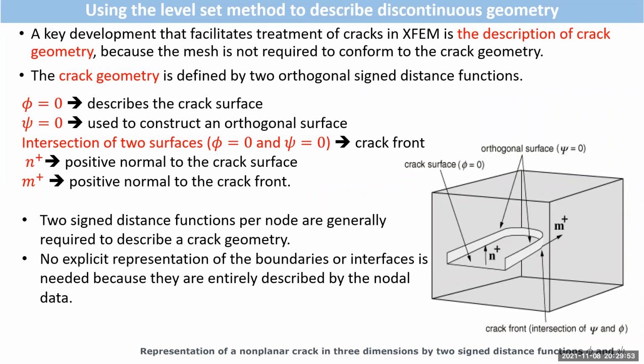But extended finite element, we are saying it's independent of the mesh. The mesh is represented only through nodes. We are saying here it's independent of mesh. So we have some other procedure in order to identify the crack geometry. Extended finite element has a different method called level set method. So instead of depending on nodes to define the geometry or define any part, extended finite element depends on something called level set method, which is used to describe the crack geometry, and that's why it's independent of the mesh, right?